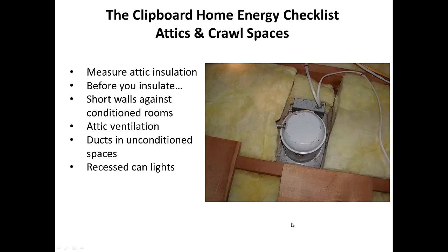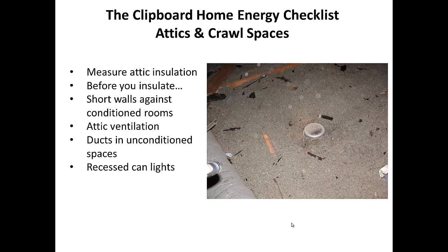Now there are things you can do for that that we'll see in a second, but here's another recessed light fixture where they haven't done a good job of keeping insulation away from it, and that could present a fire hazard right there.